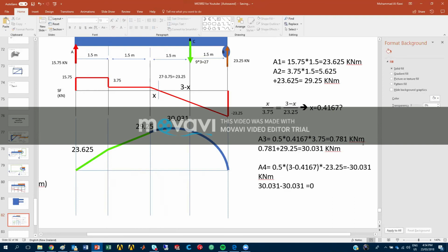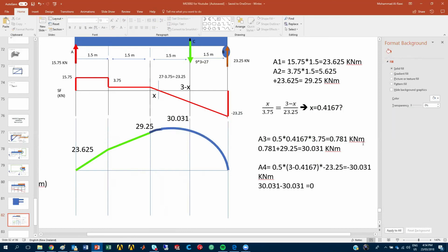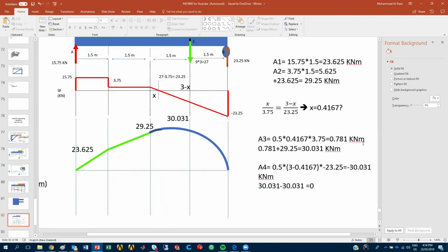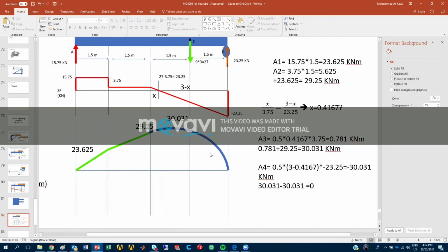So again, thank you to Thais and Matthew. And that's what I was meaning. So thanks. Yeah. So now it's corrected, looks better. And that's one of the things, guys, you always need to remember in your test. When it's a triangular load or UDL, on the bending moment diagram, it should always be a curve, parabolic. Otherwise, you may lose marks like I'm doing now for myself, because of many things going around. So that's how you do it. In your test, I don't really expect you to have a proper parabola, but as soon as you show it a bit curvy, that will be more than acceptable.